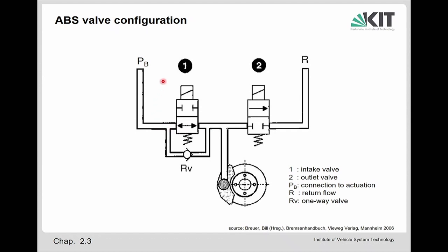This is a situation where this system comes into play. If the system recognizes that the brake is not operated in the optimal way, then it is able to close that valve, in order to avoid that the increasing brake pressure created by the driver is transmitted to the wheel brake. So you can just close that, so that even if the brake pedal is pressed harder, this will not increase the brake pressure at the wheel anymore.